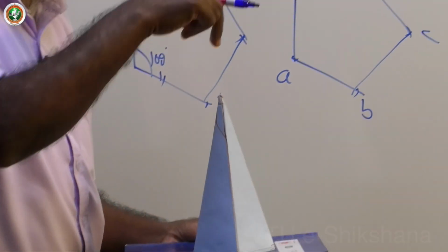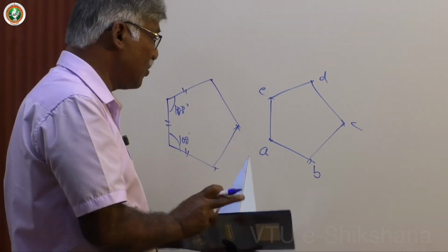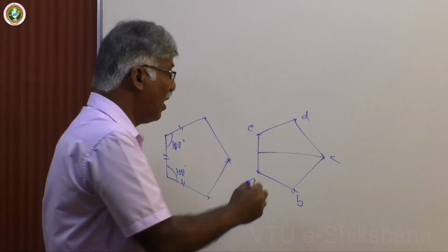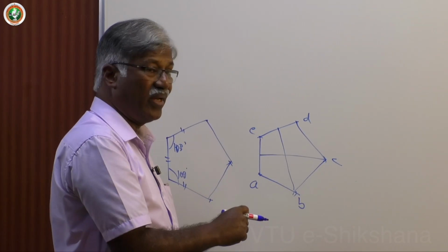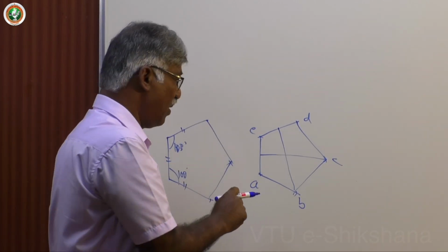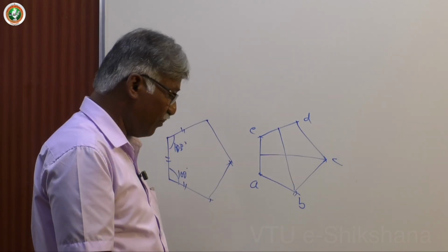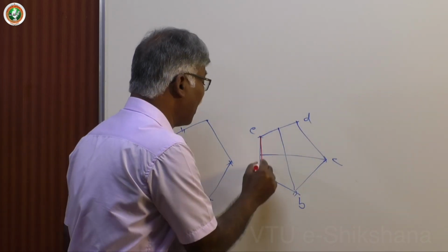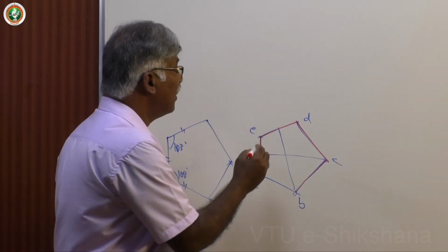Next, what about the top view of the slant edges? To identify the center, you have to draw two perpendicular bisectors, preferably one horizontal and any other one. Even in the computer you have to do this, it gives the pentagon automatically, not the center. You can identify the center, but you have to draw all these. Now how to complete the top view? The top view can be completed by using the dark line if necessary, then draw all slant edges.